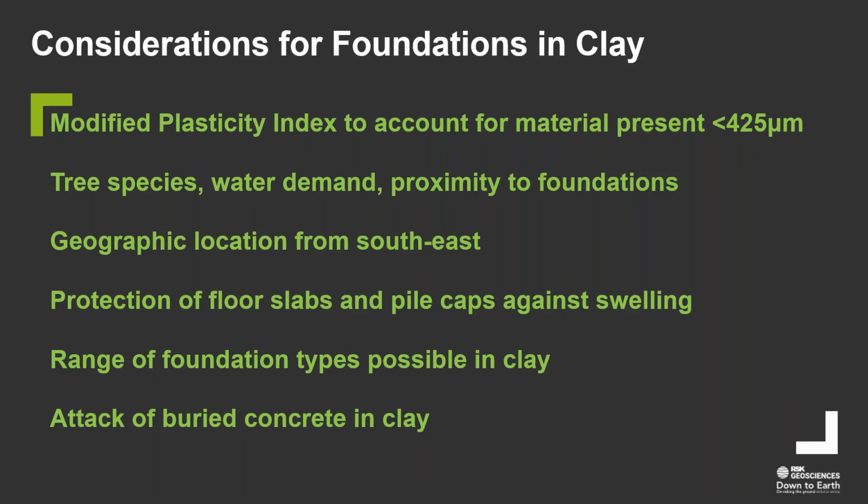Looking at overall headings and things that might be linked in with foundations in clay soil, we're really looking at what's the fraction of clay present in the soil that's going to influence shrinkage and swelling. That's traditionally done by looking at a modified plasticity index, which is the material less than 425 microns in size. We'll be looking at the tree species and then water demand, how far away from the foundations they are, the mature height of the trees, and whether they're early on in their life or later on in their life, and all of that is in the NHBC guidance.